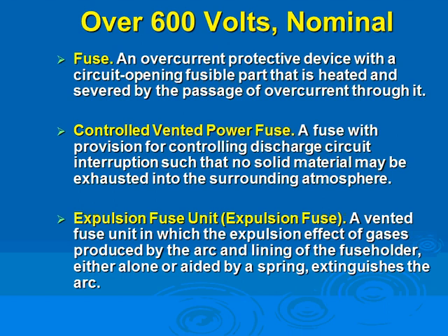What's going to happen? You imagine the impact. That's what the circuit breakers need to be able to handle, interrupting that energy at 85,000 amps. It's a huge energy, big mess. It's going to happen, so you need to interrupt the arc. They use either air for low voltage, then for high voltage, they use oil.